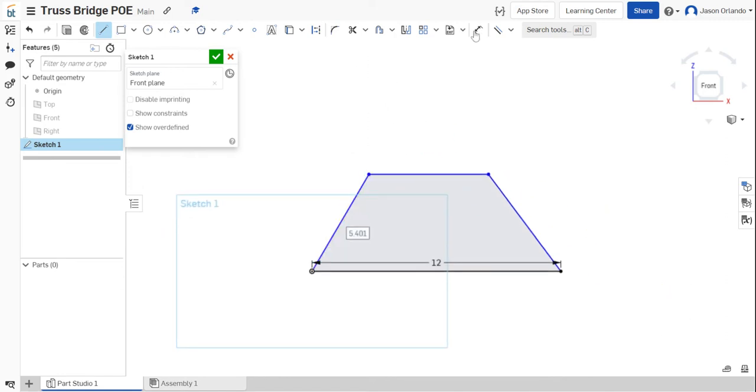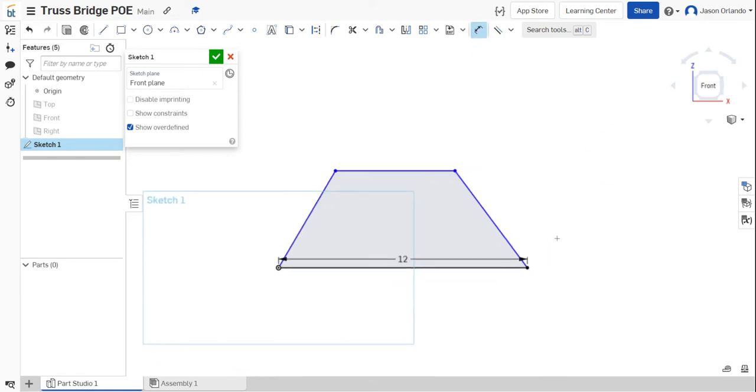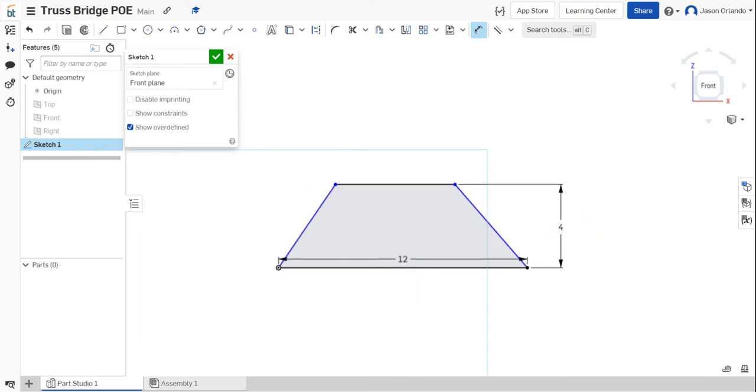Okay, so I've made a shape. I'm going to use the dimension tool to, I think Onshape doesn't want me to. I'm trying to hit escape. I think when I'm using my screen recording, some keys don't work the same. I'm going to dimension using the two endpoints to get the vertical distance between those, and I'm going to make it 4 inches.